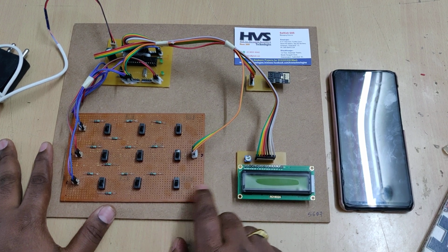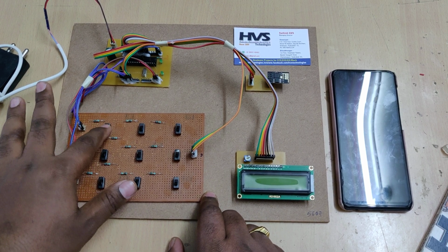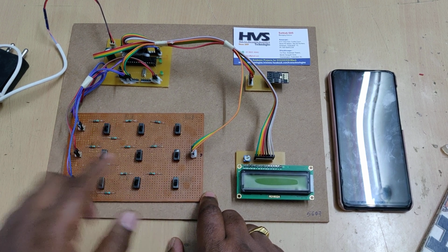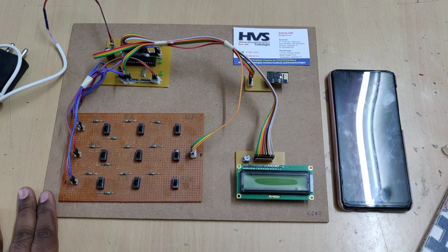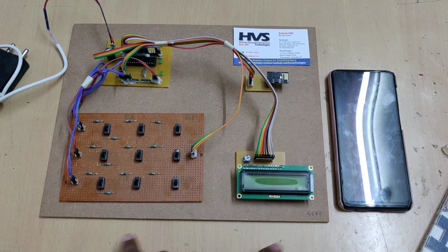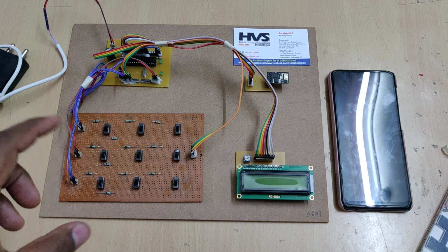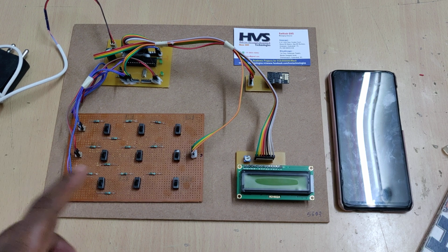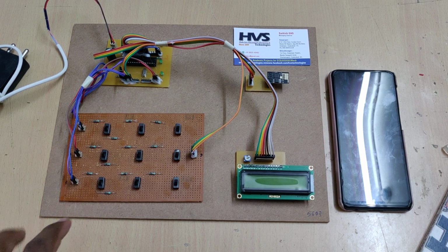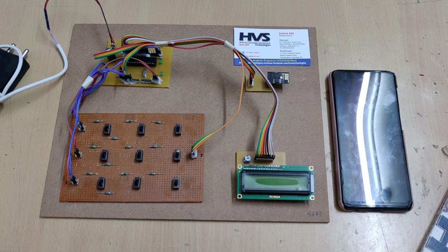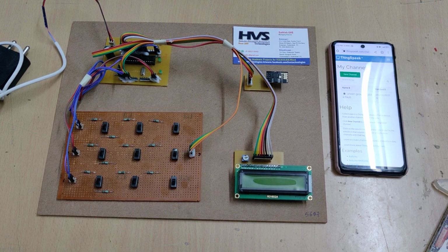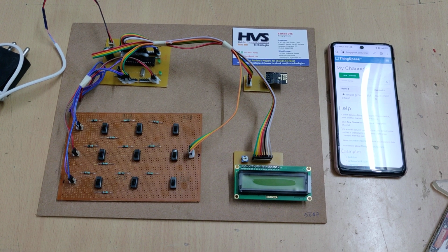After noting down the voltages, we assume that if you are getting voltage V1 here, then it's a fault at 1 kilometer. If your voltage is V2, then we assume the fault is at 2 kilometers. Like that, in real time also, if the length of the wire is 3 kilometers, and we make a short at 0.5 kilometer, how much voltage are we getting? If it is 1 kilometer, how much voltage are we getting? So we need to make a tabular format, and then make a proportional formula. Then, based on the voltage drop, we estimate the distance of the underground cable fault. In that formulation manner, we are going to make this project in real time also.